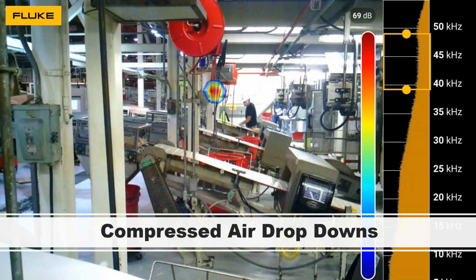All right. The more we do this, the more we find interesting places and obvious places that there are going to be air leaks. This can really help your inspections when you're doing compressed air leak inspections. Anywhere that you've got a drop down from your main ring or your main feed lines onto a production floor, look at any connection point. Inspect the entire length of the hose.